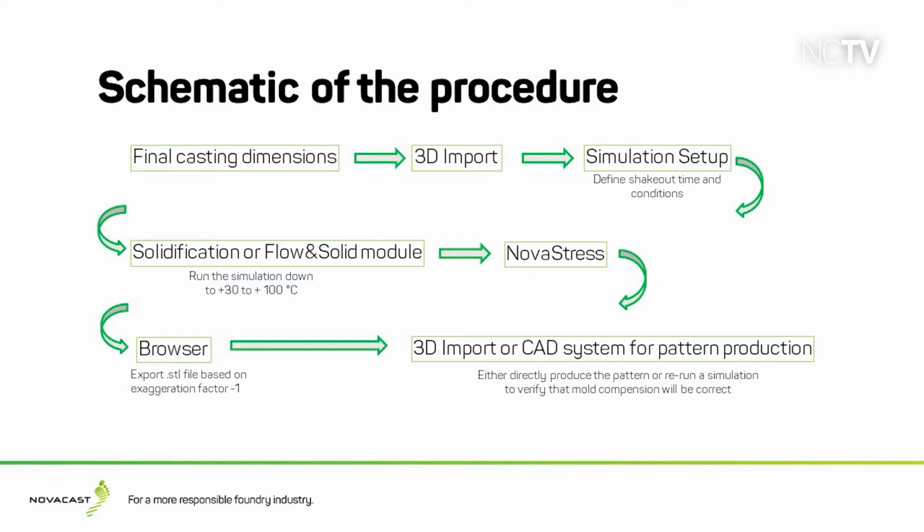Then you go to solidification or flow and solid. Of course, you can run it with flow and solid as well if you want to. Run the simulation down to plus 50 or 100, or as near to your room temperature, which you have set at the moment, as possible, but at least somewhere in this range.